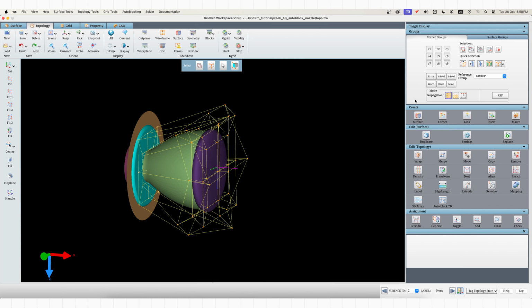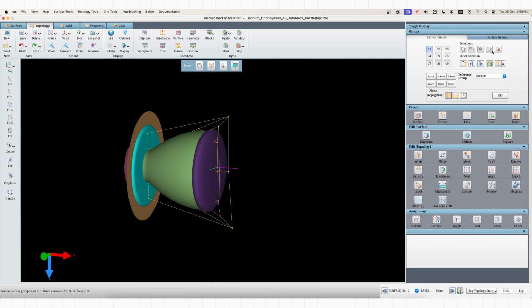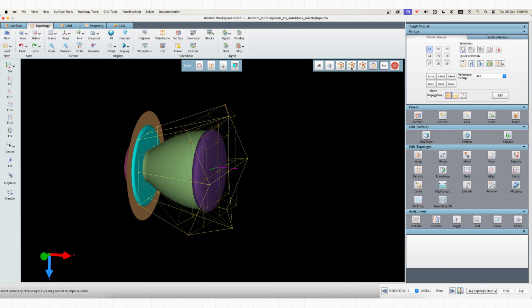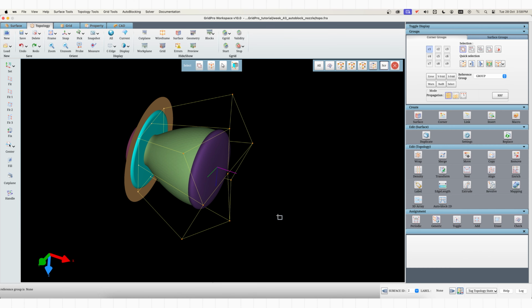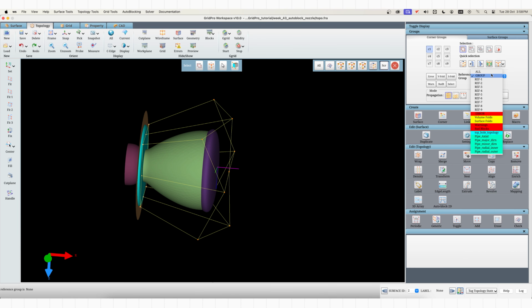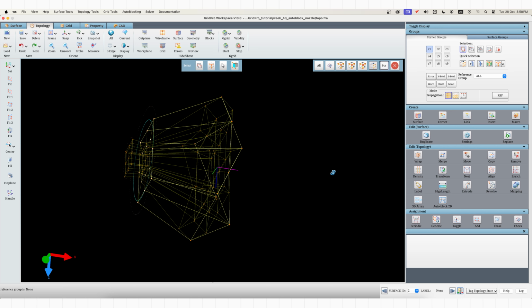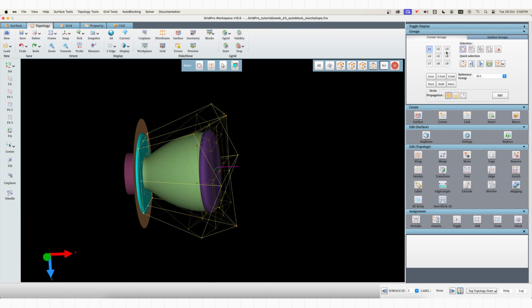Extending the topology to the domain. Group the corners to be copied to the domain by clicking on the External Unassigned Corners button. We will retain the corners only at the nozzle outlet using the Retain Selected Corners button.